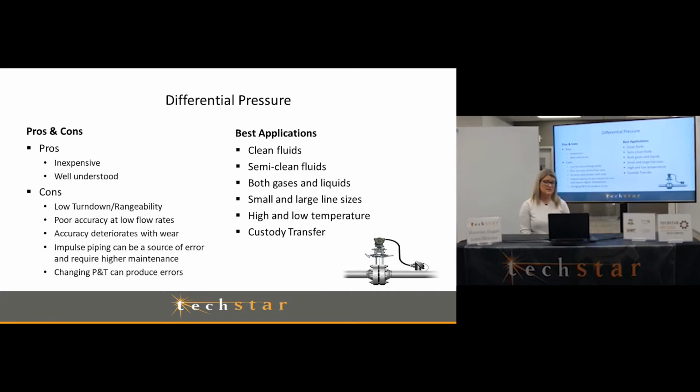Some pros for differential pressure is that it's a very old technology. It's very well used in almost every kind of industry. It's well understood, and it's fairly inexpensive. The problem is that it can have some low turn down. It doesn't have a great range, so you'll just need to be aware of that whenever you're specifying these. And it does have some poor accuracy at low flow rates.